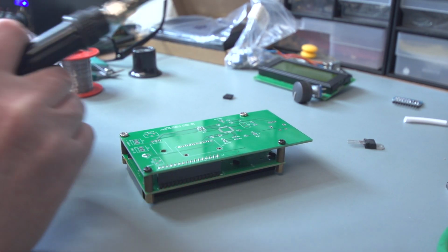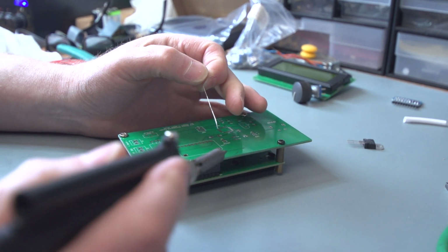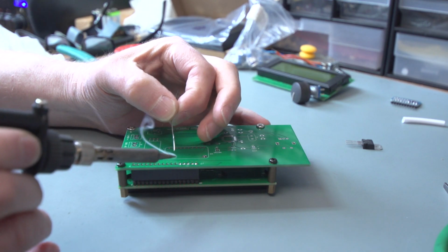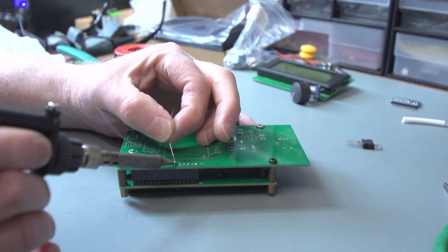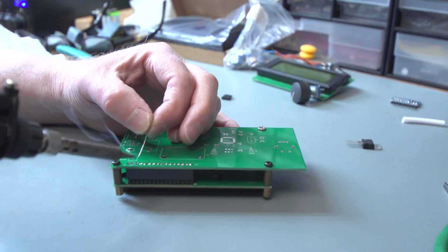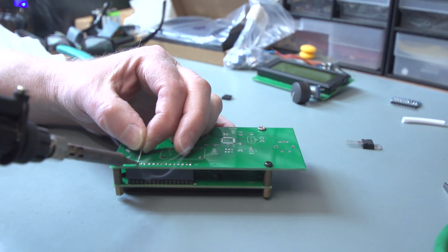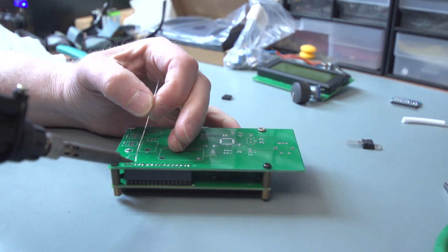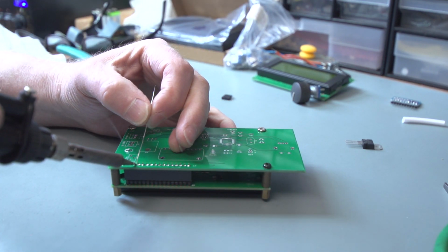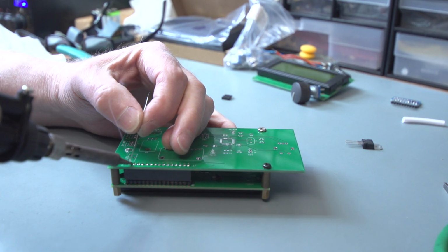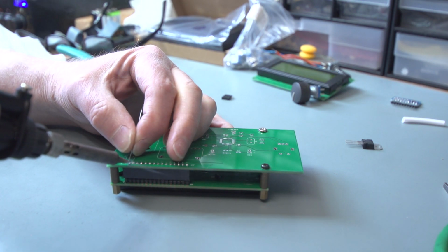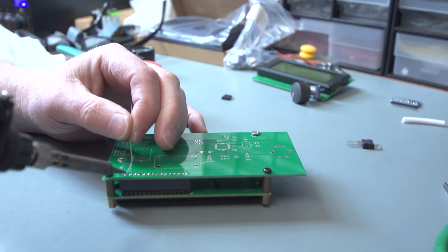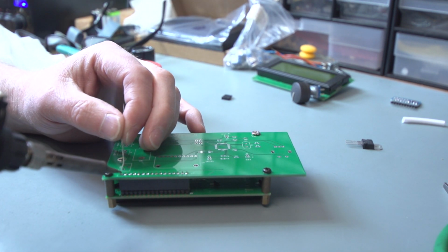Okay, let's do a bit of soldering. Here we go. Hope you can see all of this. When you solder to the earth, like the ground connections, you need a bit more heat, because it works a bit like a heat sink, and it sucks the heat away from the pin, like this one here on the end. I'll just retouch that a little bit. There you go, this one on the end.